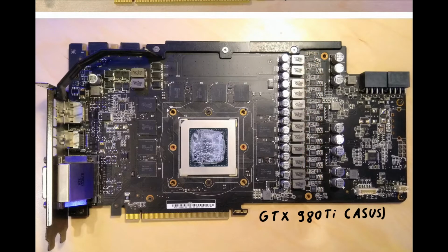So again, these power stages integrate MOSFETs, but it's actually not a 12-phase, it is a 6-phase, because this VRM is doubled by these little things right here. These are doublers, and to understand how they work, you have to understand PWM controllers. The PWM controller is this right here, and these PWM controllers are not just good to find out how many phases you have. They are also a really important part of the VRM, and they can tell you how good your VRM is.